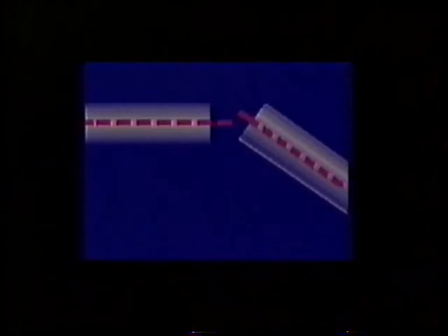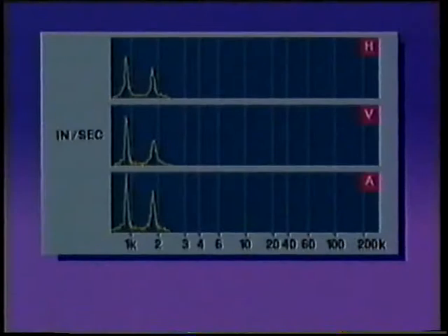These 2 types of misalignment problems, angular and offset, can exist together. In fact, this is much more common than finding angular or offset misalignment alone. So, the presence of both radial and axial vibration is an indication that misalignment may be the problem when high amplitudes of vibration show up at both 1 and 2 times RPM. Usually, the amplitude at 1 times RPM will be higher because angular misalignment tends to be more severe.